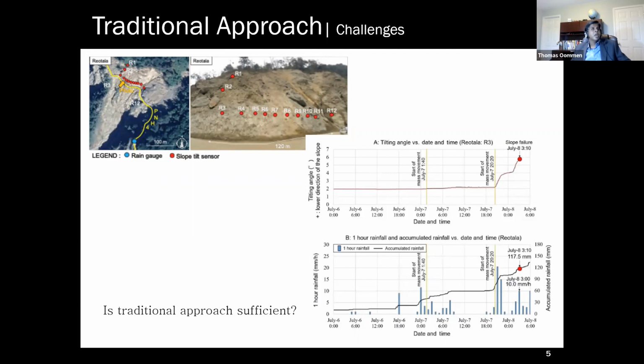So before the slope failure, you can actually detect where that slope is tilting, and you have an early warning system to reduce the risk that the slope failure could cause, particularly say if it is near a dam or a road network. You can actually stop the traffic, or say if you can evacuate people from downstream areas of the dam. So you can actually reduce the risk if you have accurate early warning.